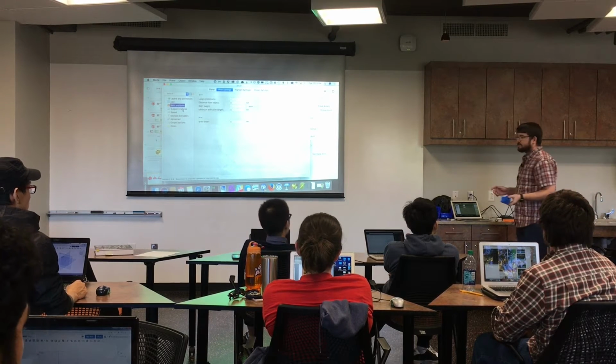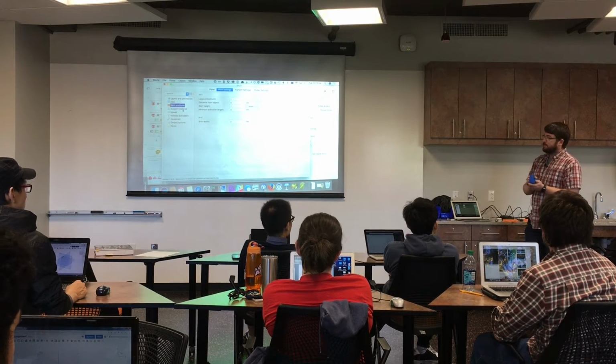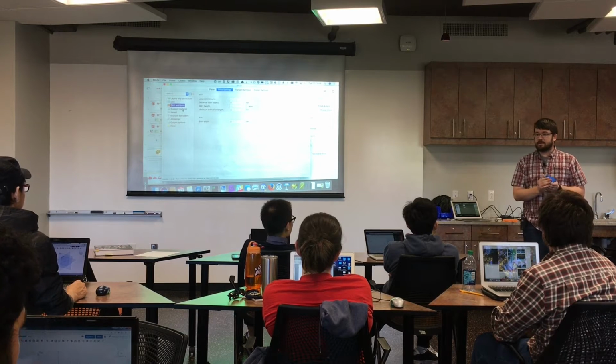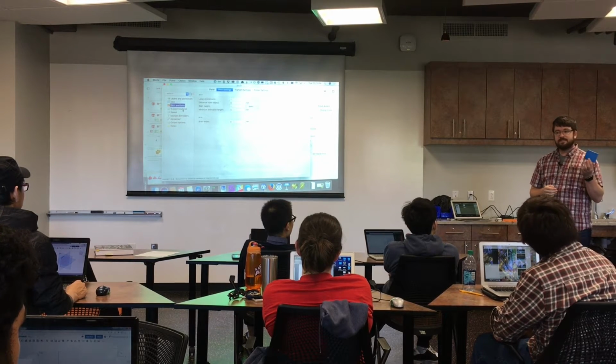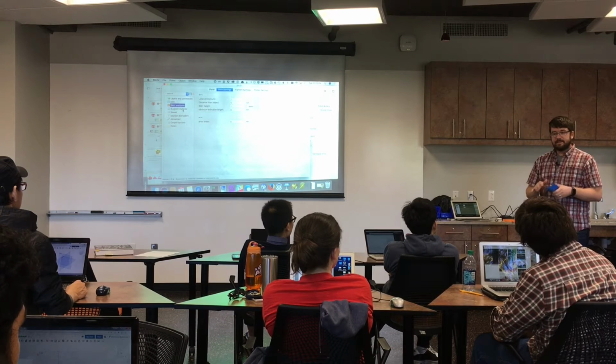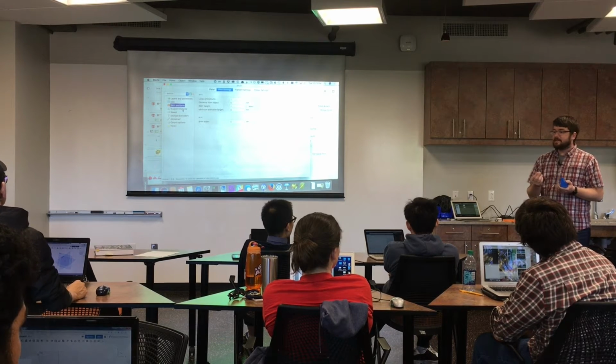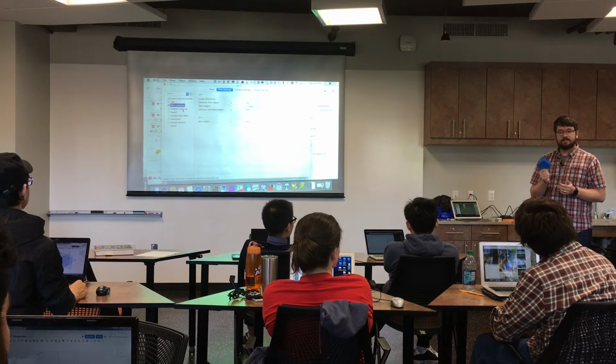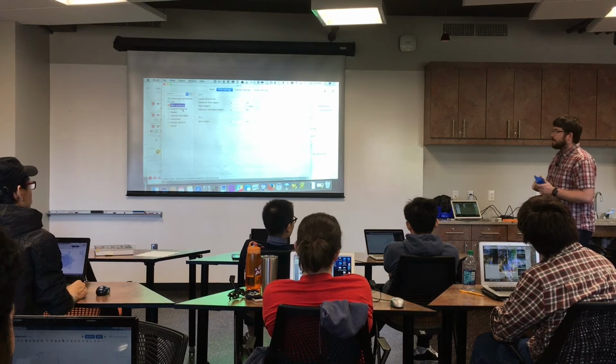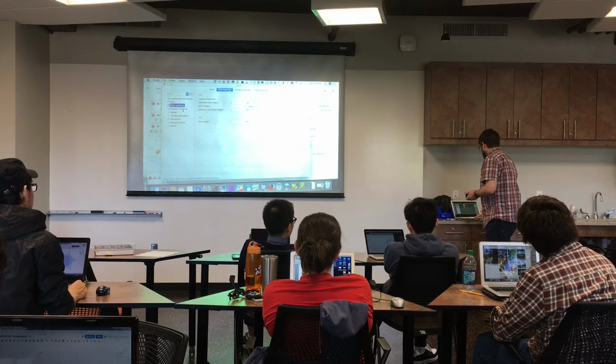So there's a lot of tricks. And for example, to get parts to adhere better to the bed, a lot of times we will use a combination of acetone and dissolved plastic and rub it on the bed. And the acetone will evaporate and leave this kind of tacky surface on the bed that this sticks to better. So there's a lot of tricks that are used in 3D printing.